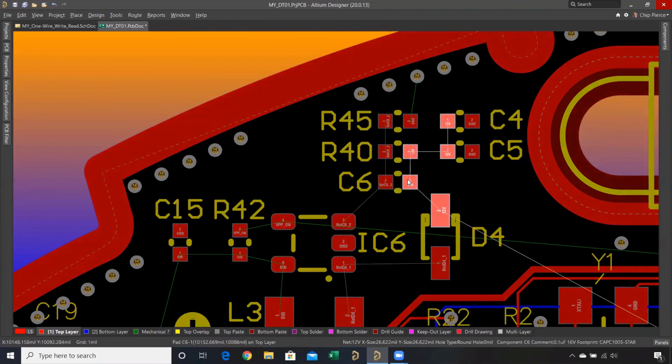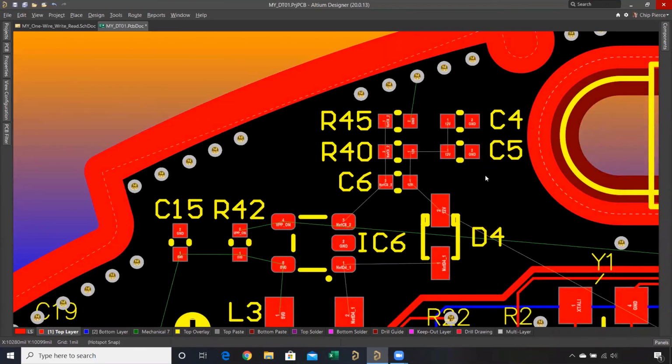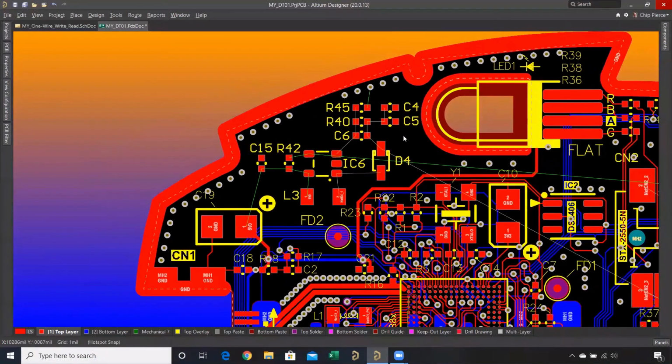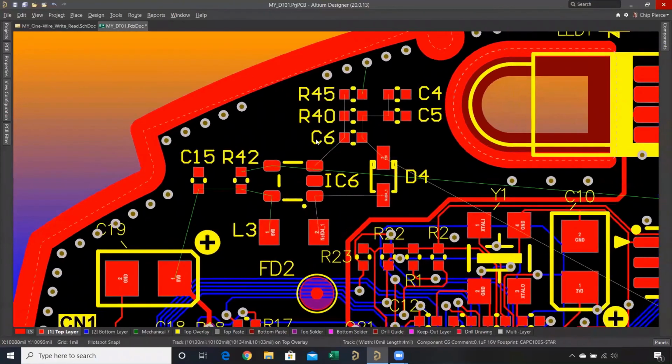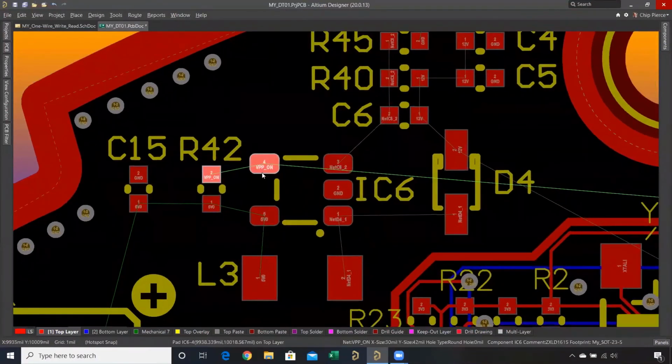You see that? Basically I could see if I wanted to run a design rule check on component placement there, but that falls out of the scope of this webinar just a bit. It's all about placing components here, so that you use the connection lines as a guide. And I can see I don't have any crossovers except one for this net here called VPP on.